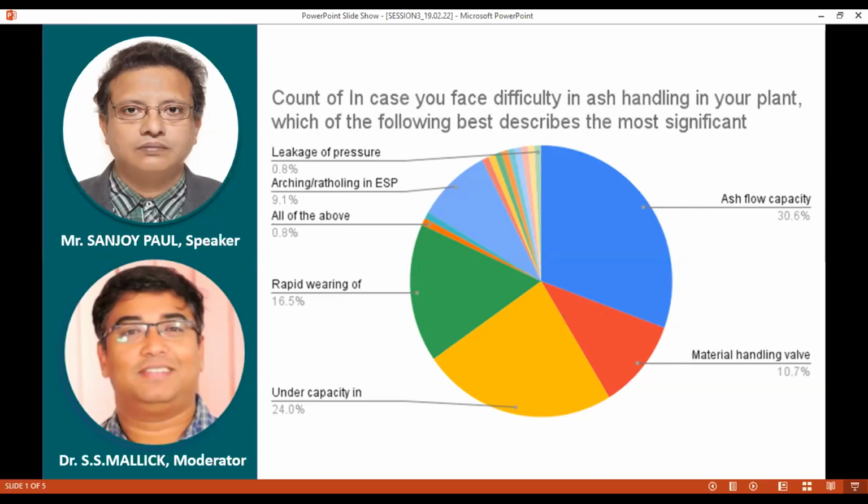It causes more erosion and corrosion to the material it touches. So suppose in the flow, if the velocity is too high, if the impingement of the ash particles is very high, and if the flow is not smooth, then at a particular point or region, these ash particles hit very hard and the erosion takes place.